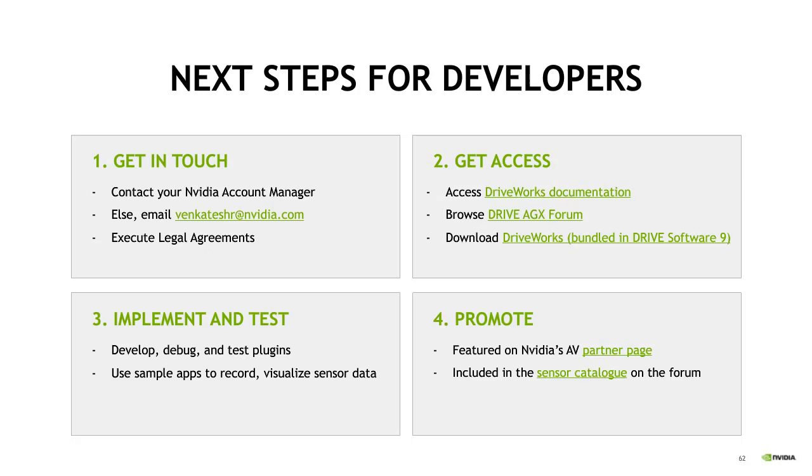While you are on our DevZone site, you can download the NVIDIA SDK Manager and install Drive software, including DriveWorks, on your Linux PC. Our SDK Manager walks you through the process and installs DriveWorks on your computer for you, so you can just get started with development. Once the SDK is installed, I recommend you compile and review the DriveWorks samples, which are fully functional demonstrations of DriveWorks capabilities. We provide the source code for the samples, making them a great starting point for your development.